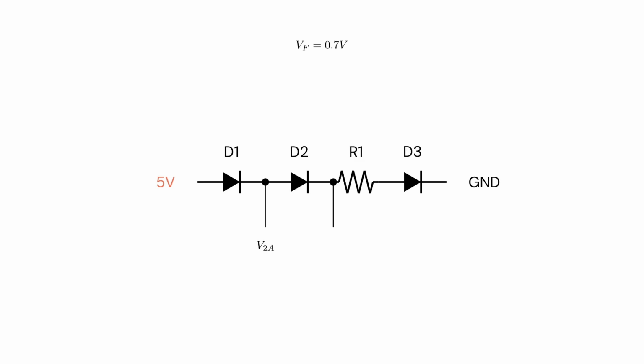The cathode voltage will be at least the anode voltage minus one forward drop. It cannot be below that because in that case the voltage drop will be very high and the current too high, but that's impossible because you started by limiting current as I told you to, right? In the same way, the anode voltage will be at most the cathode voltage plus the voltage drop. That gives you upper and lower limits for the voltages at different points of your circuit. If the diode is forward biased, the value will be the boundary.